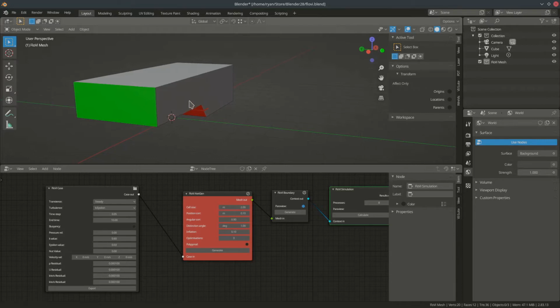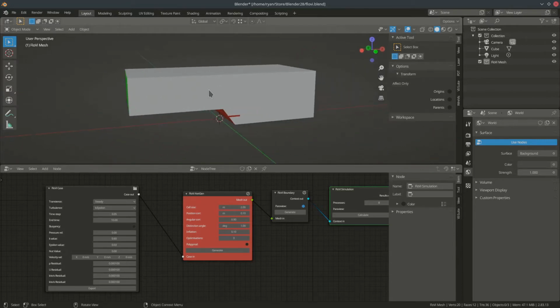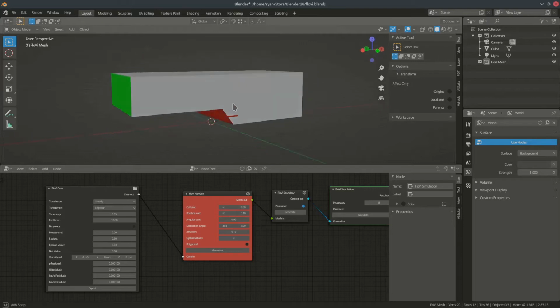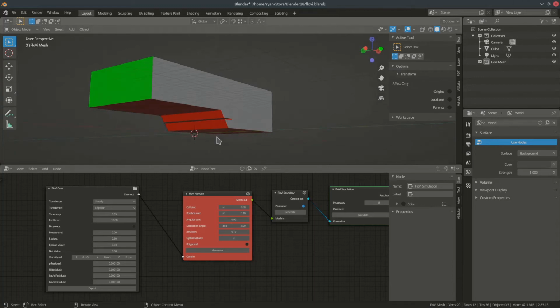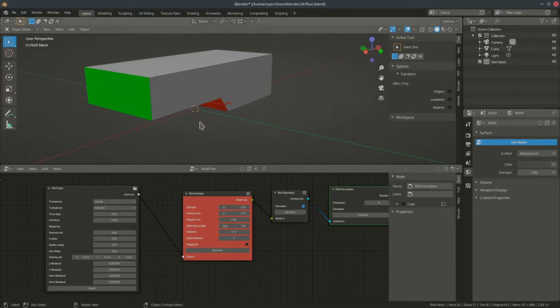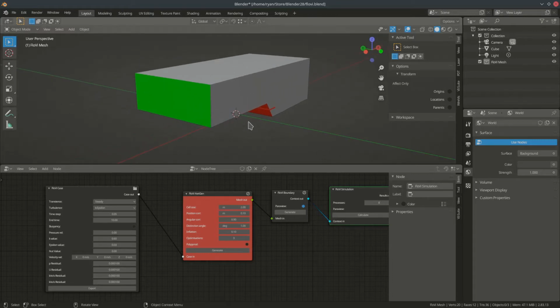So I've got here, and this is analysis I did for work of Brighton seafront, and this geometry represents the complete domain that we're going to be doing our simulation within. Now there are some important things to remember when specifying CFD domains and CFD geometry. The most important thing is that the geometry must be manifold. It must form a complete shell, which in simple terms means that every edge has to be connected to two faces, and there are no gaps within the geometry.